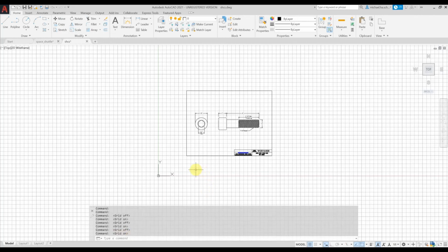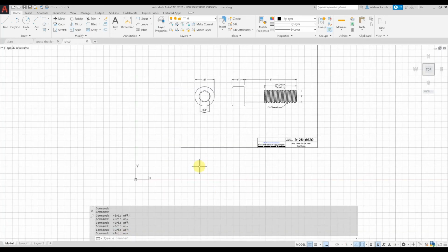Okay. You can also snap to the grid by pressing F9 or using this icon. F9, snap is on, and by pressing F9 again, you can turn it off. Okay. For instance, to practice on that, let's grab line command and let's press F9 to turn on the snap. So as you see, you can snap from one location on the grid to the next location and so forth, right?